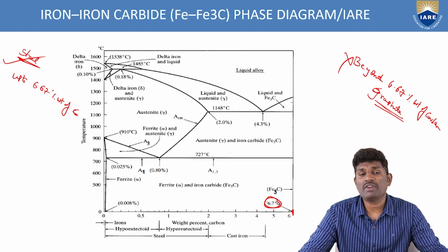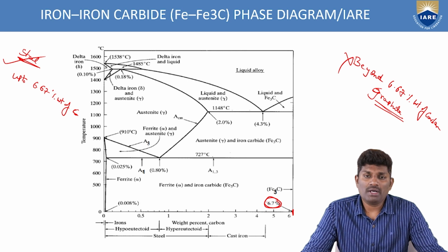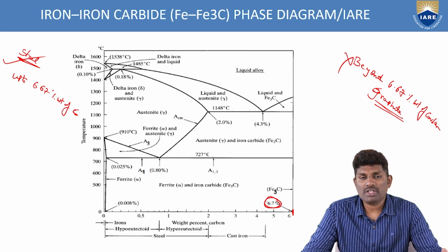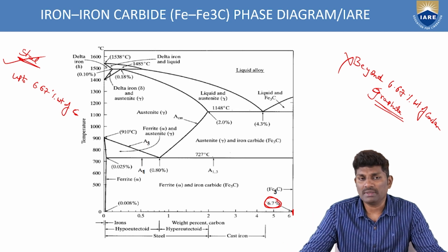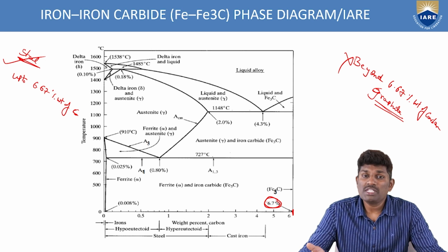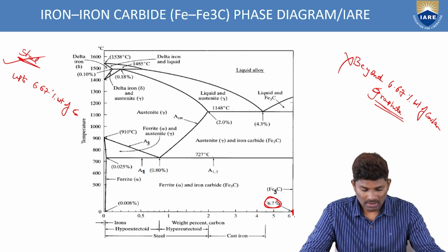That's why this iron carbon phase diagram is very complex. When you compare it with any other type of phase diagram, it is very, very complex and has different types of crystal structures observed during the cooling process. And also, if you increase the weight percentage of carbon, it converts to another type of steel. So which steel are we considering? We are considering up to 6.7 weight percentage of carbon only. That's why we are restricting our phase diagram from 0 to 6.7 weight percentage.